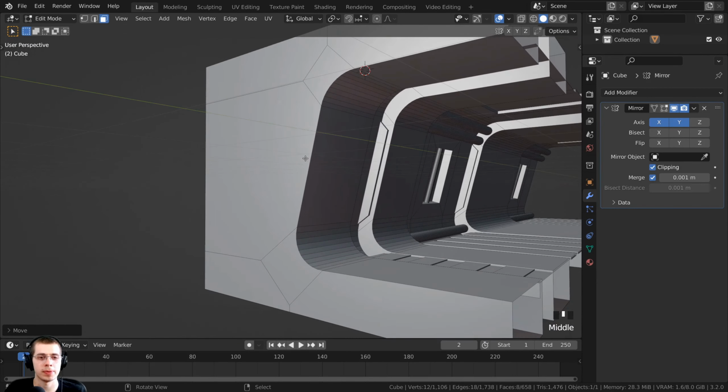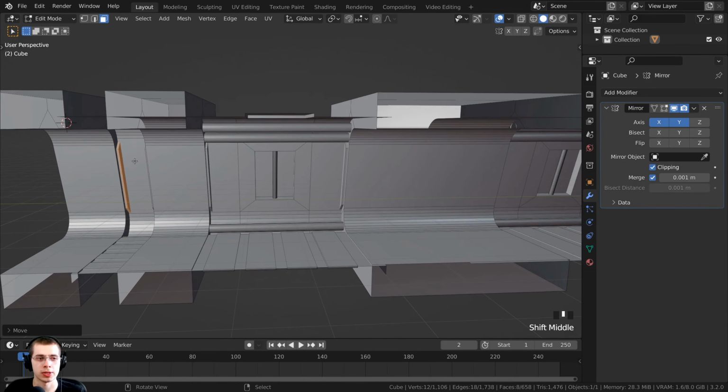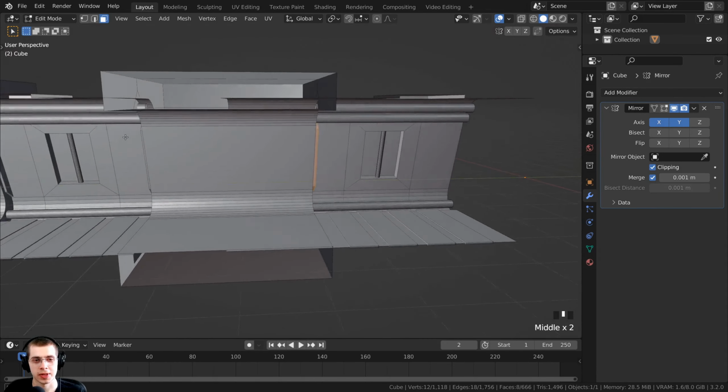And then this piece right here is going to be connecting with the mirror, so we don't want to put that there. I'm going to press Shift D to duplicate, click and hold with your mouse wheel to constrain it to the y-axis, and then navigate over here, and I want to just stick it right in there. All right, that's looking much better. So that's looking very good.